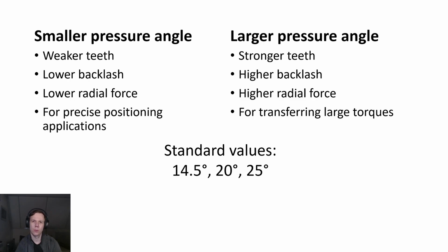Now, first of all, if you choose a larger pressure angle, you will get stronger teeth. And if you choose a smaller pressure angle, you will get weaker teeth. And I want to go into Fusion 360 again to show you why that is the case.